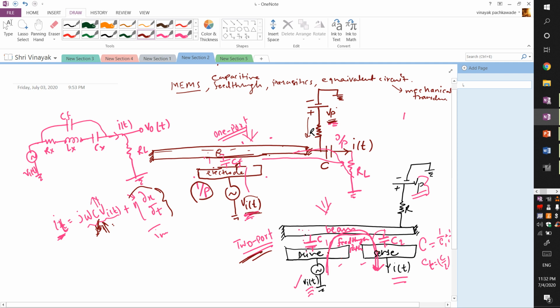That is the advantage, and an attempt should be made to reduce the component due to the feed through. Another way is to reduce omega, the frequency of the drive. If omega, the angular frequency in radians per second, goes high, the current due to feed through also dominates the current due to motion, and it's difficult to detect this current.